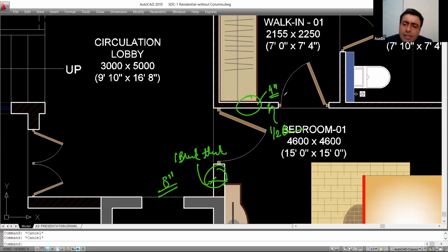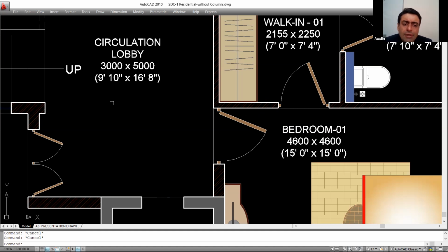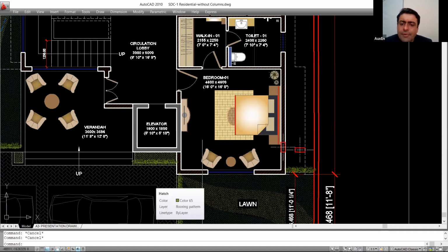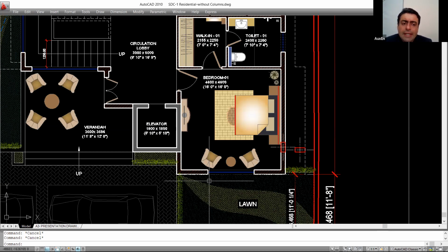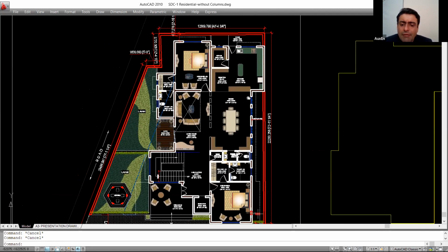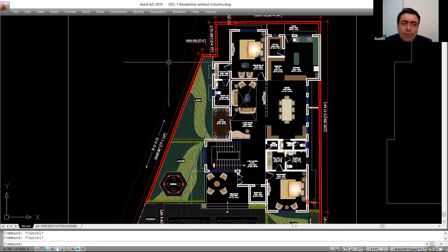What is the general convention? That all the external walls, yes, most of you are correctly saying this. The convention that we use is, all the external walls, we will try to have them as 8-inch thick bricks. Okay, let me repeat, all the external walls, I will try to have them in 8-inch brickwork. So to explain, external walls here would mean these walls.